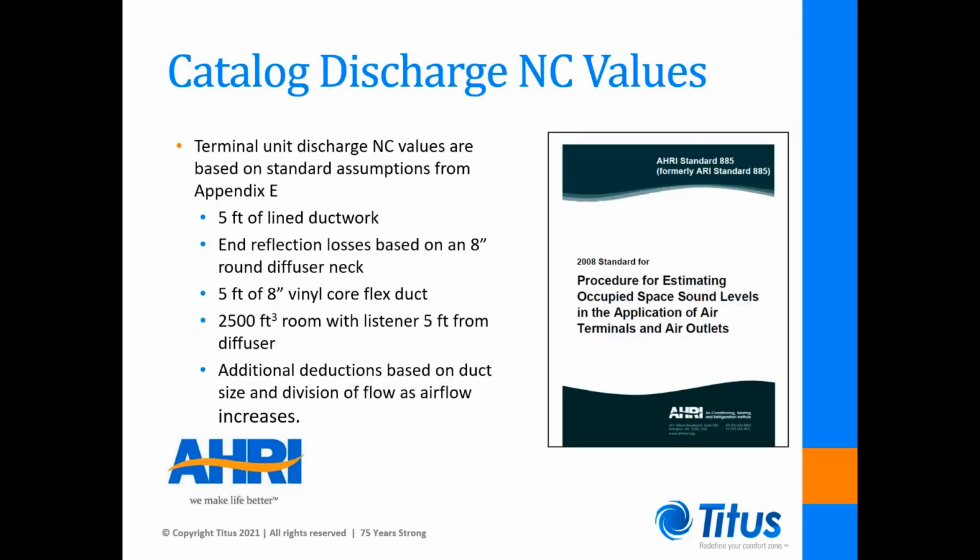The standard attenuation assumptions for discharge sound are more complicated because there's more elements to include when considering ductwork. As always, there's the environmental adjustment factor. Then there's lined ductwork assumed to be 5 foot long with 1 inch thick fiberglass lining.